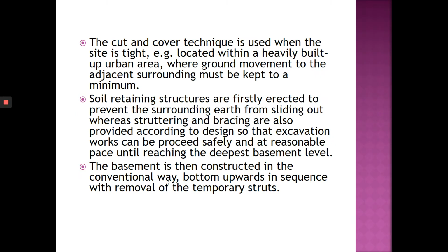Okay. The cut and cover technique is used when the site is tight, located within a heavily built up urban area where ground movement to the adjacent surrounding must be kept to a minimum. What the point is saying here is that normally we use the cut and cover technique at very congested areas, for example, KLCC area, Ampang area, whereas Bukit Bintang probably.